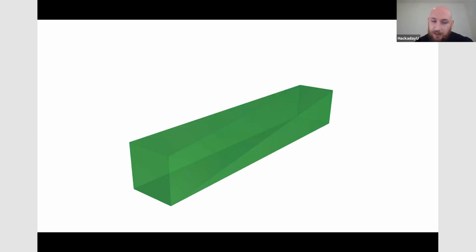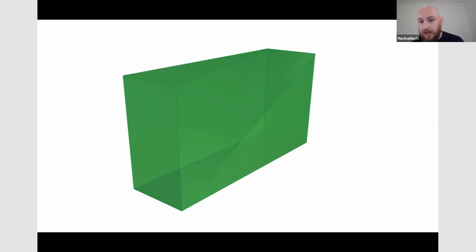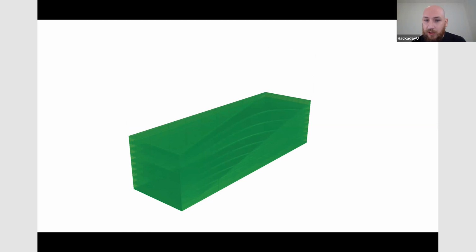In Grasshopper, it will be red if not selected, green if selected. I just did the screen capture when this was selected. But in Grasshopper we organize it in a different way, and everything is flexible. So we can change the edges, the width, the height, and the same model can then adjust to any settings we give it. We're going to do some surface divisions as well, and the contour, where you could put the number of floors as a variable and use a slider to change the number of floors and organize your model differently.